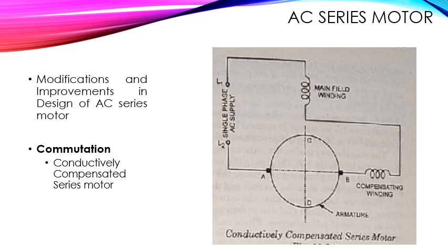In single phase AC series motors, as already explained, two EMFs, rotational or speed EMF and transformer EMF, are induced in the armature conductors. So whatever the brush position may be, there is always an EMF induced in the short-circuited element of the armature winding. Hence, when the brushes are in normal position, that is perpendicular to the main field flux, as shown in the figure, transformer induced EMF is in the short-circuited element, and when the brushes are along the field axis, dynamically induced EMF is induced in it.